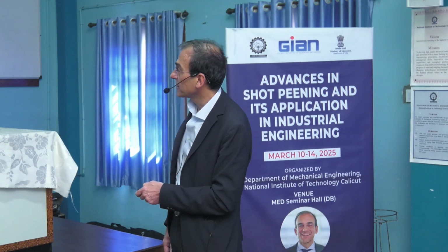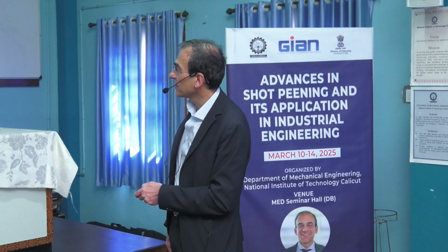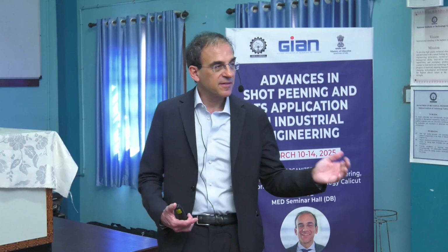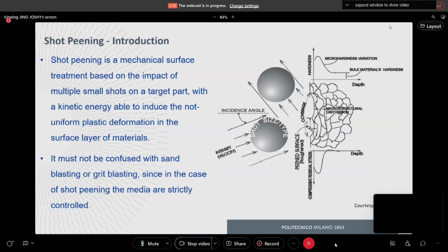Like for shot peening, there is a compressive surface residual stress, then the peak of compression under the surface, and then the residual stress decreases and becomes positive, but a certain depth depends on the shot peening parameters.